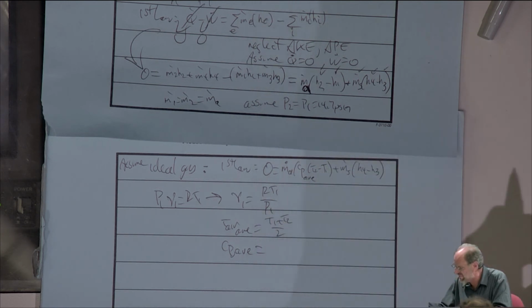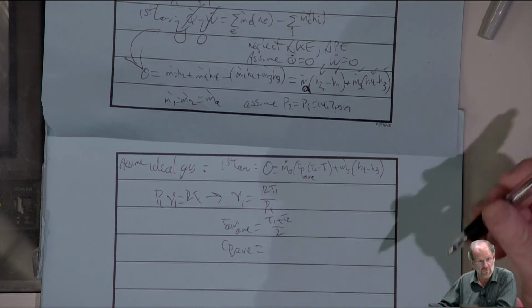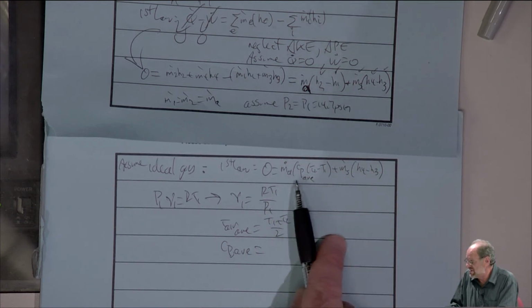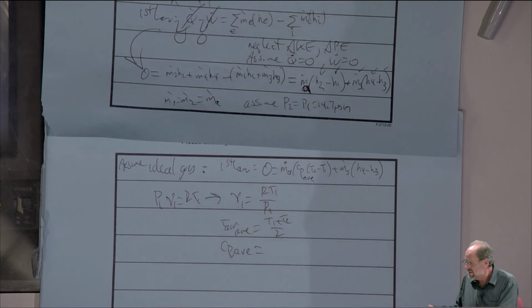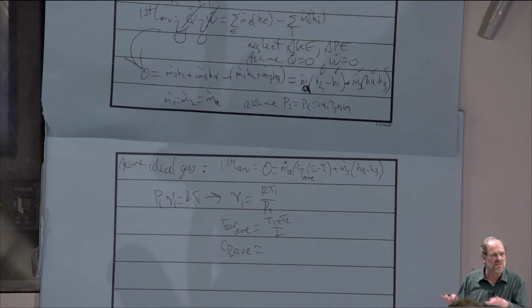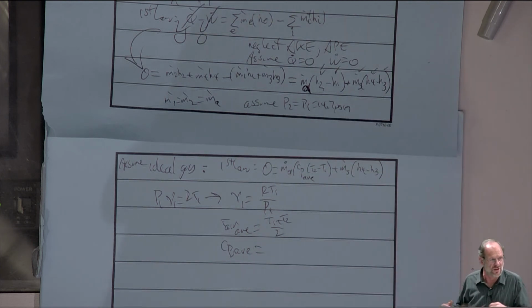Since we do have the temperatures at point 1 and point 2, we can find the average temperature, and we can find Cp at the average temperature, which would be the most accurate way for us to find the enthalpy change. All right, any questions at this point? There are a lot of things we've had to assume. This is not an easy problem, but mathematically it's not difficult. It's all just junior high school level algebra, so there should be no math issues. They're conceptual issues, data issues, equation issues, but not solution or math issues. So, think about this problem.